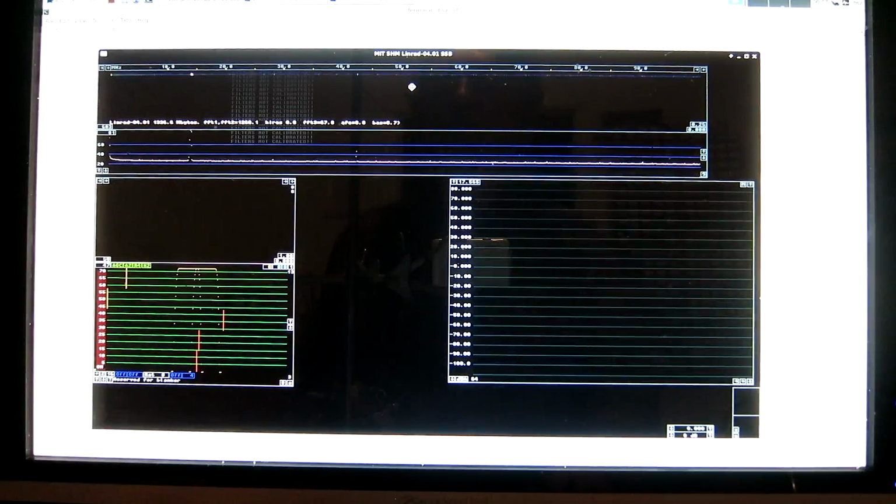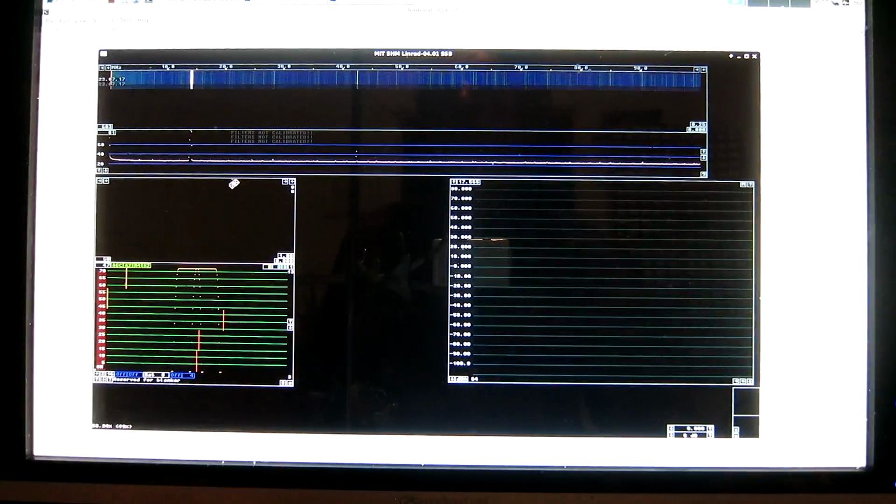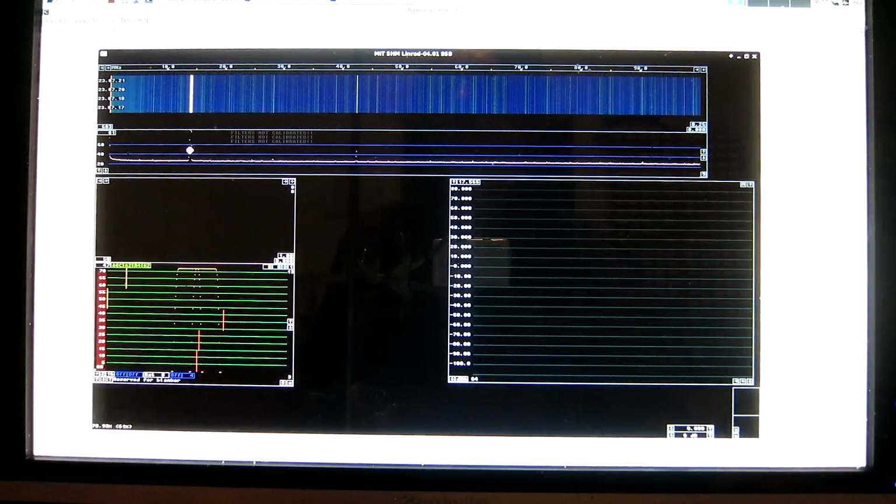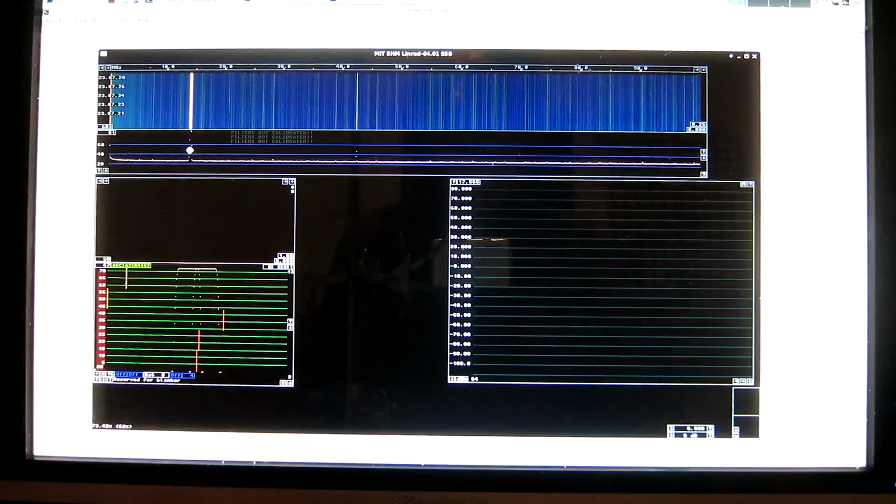That's a fairly high frequency for the baseband, but this is necessary because the transform is pretty small. The bin resolution is 6 kilohertz, and that's a fairly wide bin size. This is a limitation in Linrad at this time, September 2, 2014.